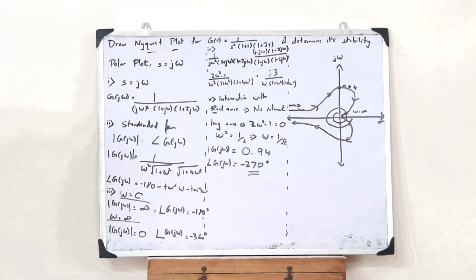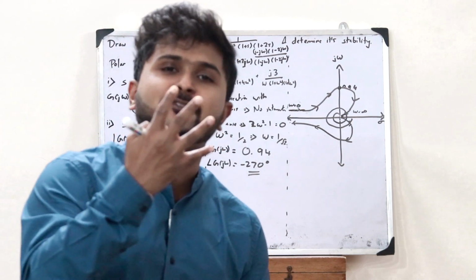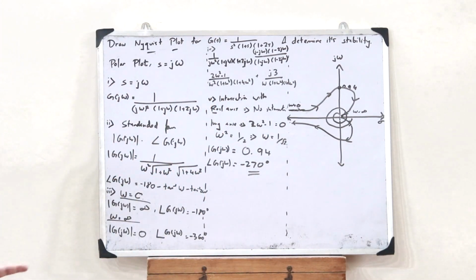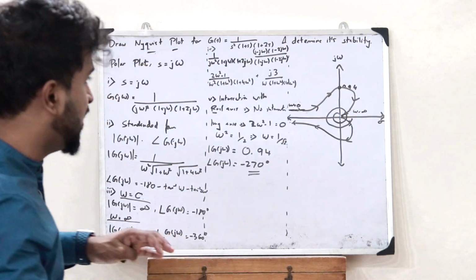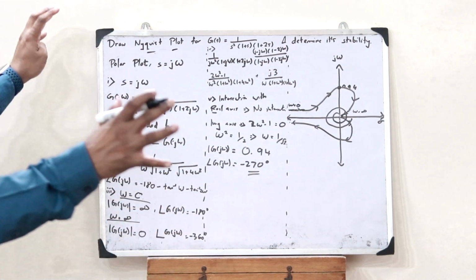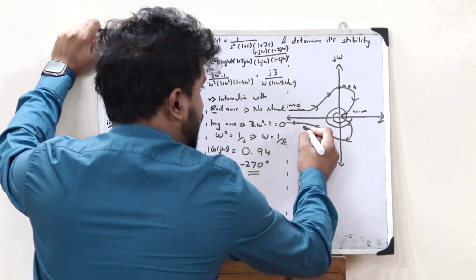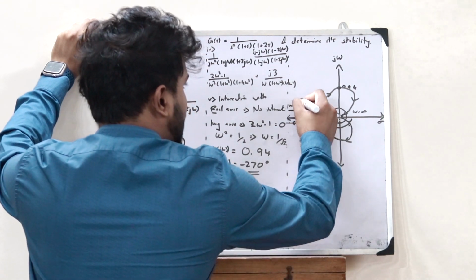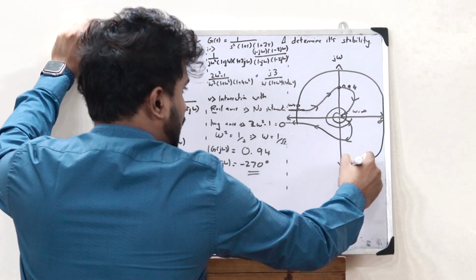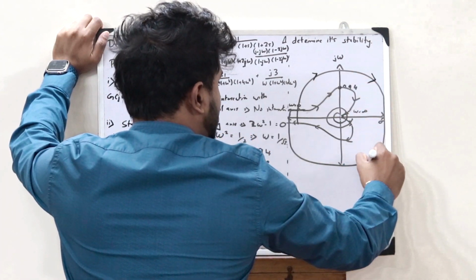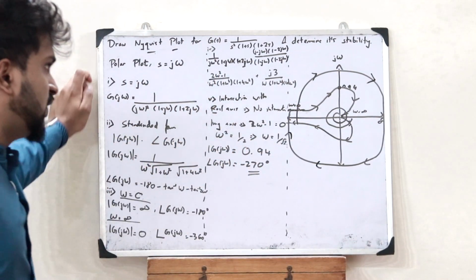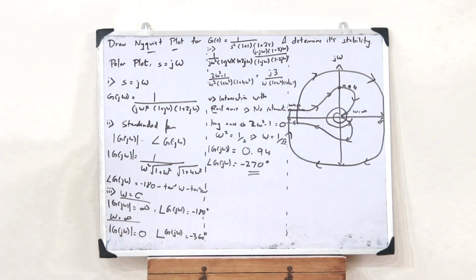Because it varies from a phase of minus 360 degrees to plus 360 degrees. And now, from part 4 of the Nyquist contour, we have a plot varying from plus 180 degrees to minus 180 degrees. So it has one circle in the clockwise direction, and here the magnitude is equal to infinity. When we plot this, it would look somewhat like this. It would originate from here, complete one circle like this, and terminate over here in the clockwise direction. So this is the required Nyquist plot that we now require.